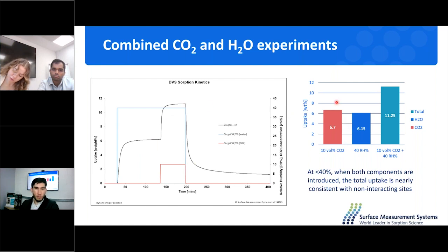If we look at the pure component uptakes at these levels, 40% and 10% CO2, 6.7% weight of CO2 if it's pure, 6.1% by weight of water at 40% relative humidity. And when the two are combined, it almost looks like you add these two together. So the material seems to be very promising for taking up CO2 even in the presence of water. And there seems to be no interference of the two below the threshold for material decomposition.